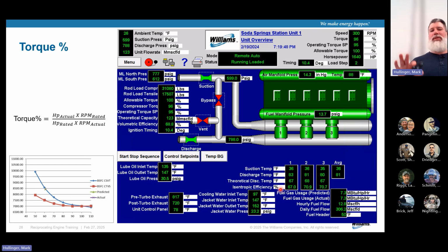So walking up to your HMI or looking at this, and you know you're doing a Windrock or a resonance analysis, and you see 10 degrees difference on here, you know something's hot in your compressor. Then you're going to walk up with the earphones and put it on there, and then the resonance will show it again. Okay. Three points of information. What this tells you is suction temperature and discharge temperature, that's measured.